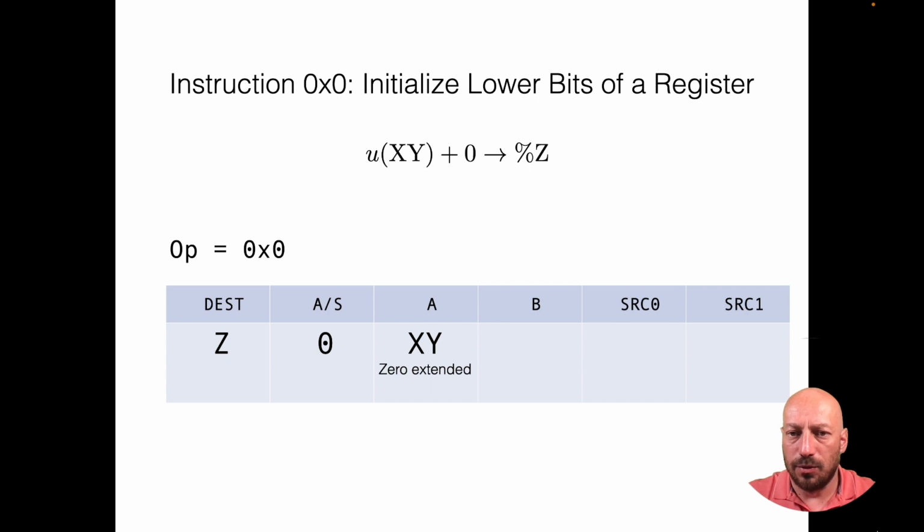The second operand should be a 0-bit pattern with 16 bits. So we just use the 0 register for that. That means we have to select in the register bank the 0 register with either source 0 or source 1. And I just choose source 0. So I will use 4 bits as input there. And source 1 is actually not needed in this operation, so I can use here any kind of identifier.